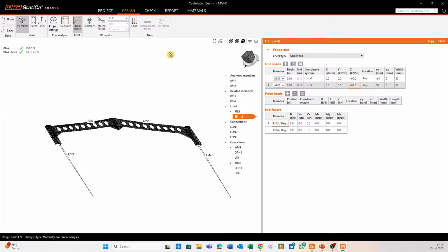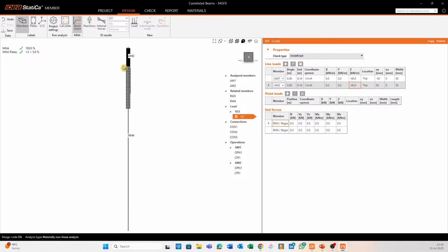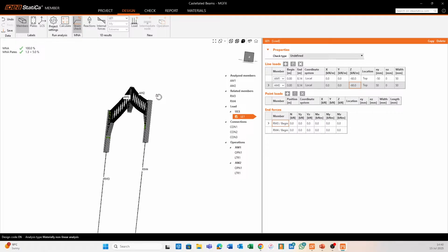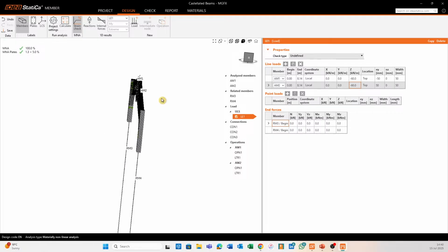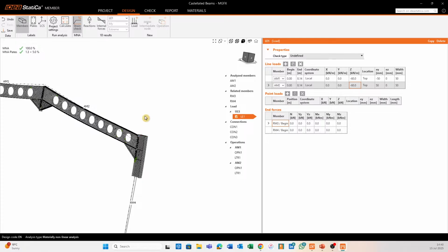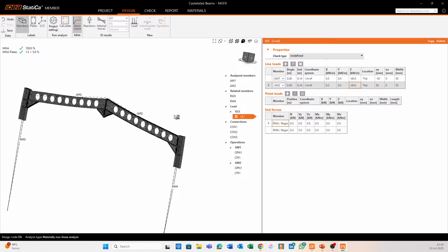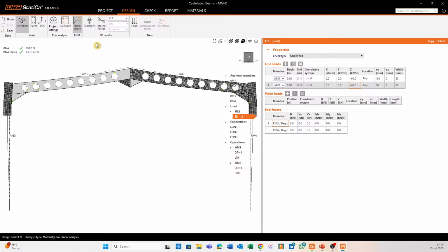Okay, so here we're at 1.3% plastic strain, which is quite good. Those lateral restraints do help, and they would. All right, so it's more realistic to have them because we would in practice, of course, have those purlins running on that top flange with cladding attached to the purlins as well. But we are at 1.3%, which means we're really pushing this beam.